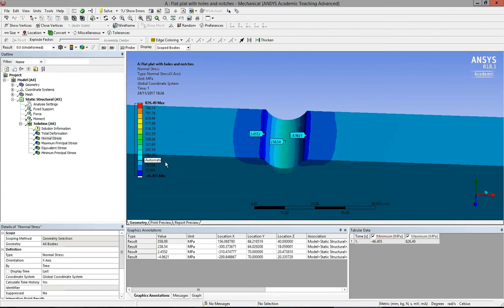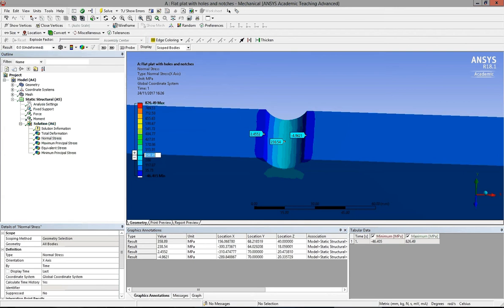You can double click on these and you can change the numbers. You can manually set the interval. So say if I want some detail between 200 and 240, I could change this one to 200, this one to 210 maybe, this one to 220, this one to 230, this one to 240.